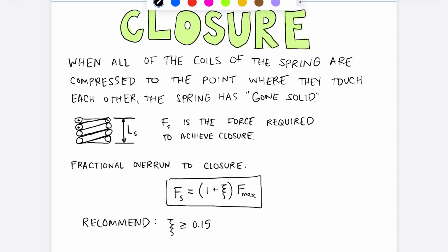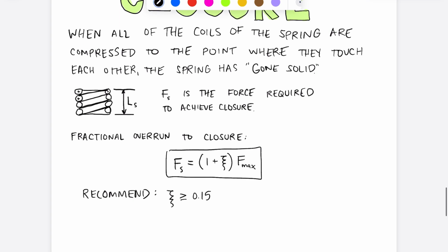I would think twice about getting a spring with set removal if you are concerned with fatigue. Remember that the mean stress that's applied in or felt in a material in fatigue has a significant effect on the fatigue life.